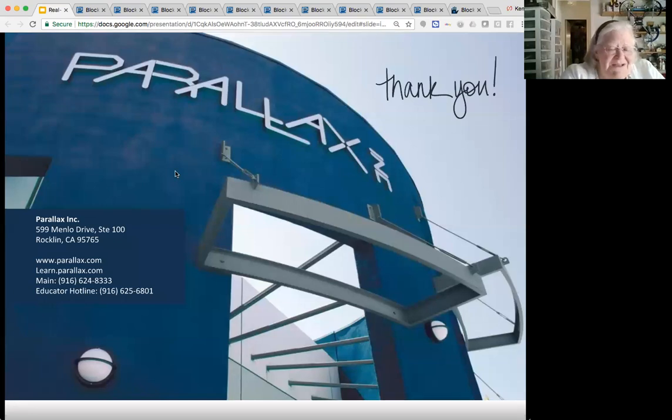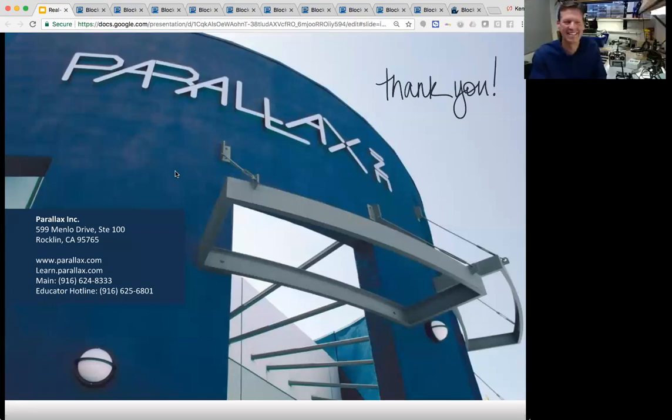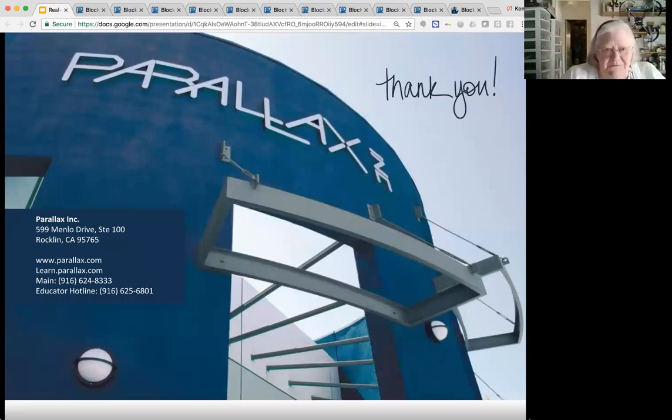So if I ever get my PID finished, you will be the first to know. I did figure out one thing. Especially since you don't have floating point, it gets too big to use Kalman filters or the regular PID filters. But there's a very simple filter called a complementary filter. And I'm getting ready to try that on the robot and see how it goes. Great. And I think it'll be fairly easy to do in BlocklyProp. I've already started playing with it in BlocklyProp. So I may soon have a working PID.